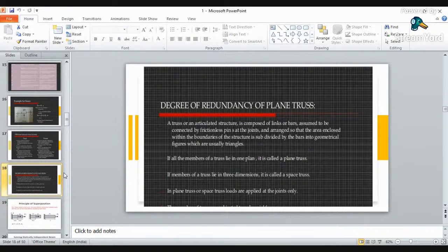While designing or constructing a truss, there are basic assumptions which guide the construction of the truss and conform to the design assumptions, to avoid unwanted failure due to the concentration of forces in the truss elements. The very first assumption is that truss members will carry only axial loads or axial forces.